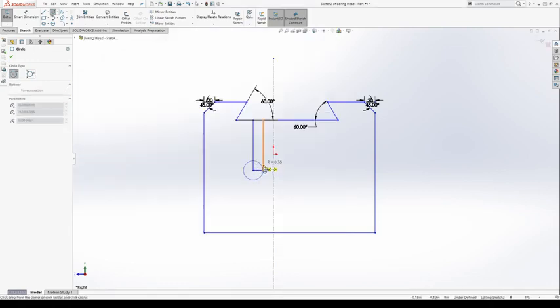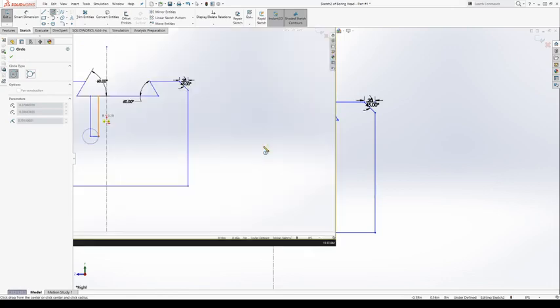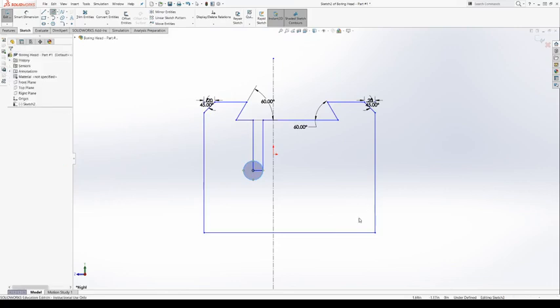So in that case, I'm just going to go here, and you can see it doesn't matter where I go on this line, because I have this line selected, it's going to use this line as a tangency, right? It's not until I get to another point or get off of that line that it's actually going to create it like a normal circle. But just by putting my cursor on this line, it's inferring that I want to make the circle tangent. There we go, tangent to this line. Okay, so we go like that, and there we go.